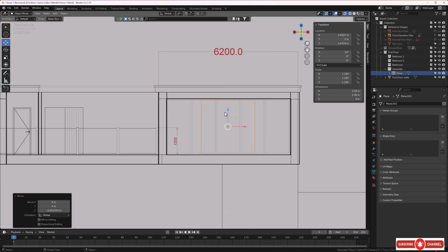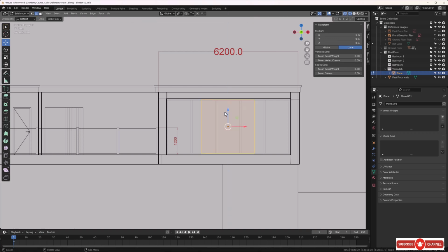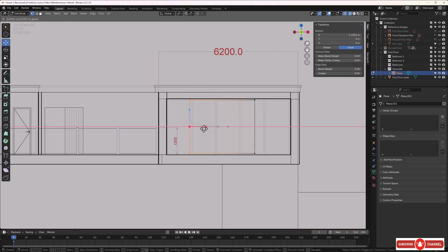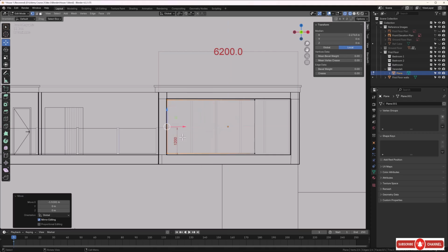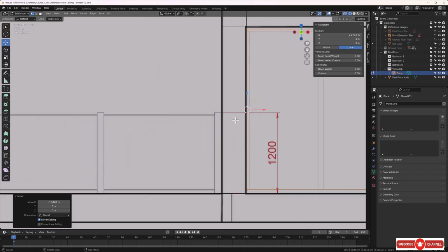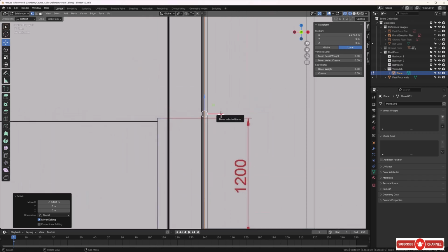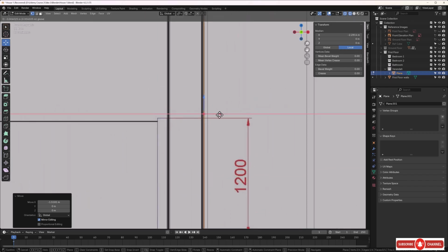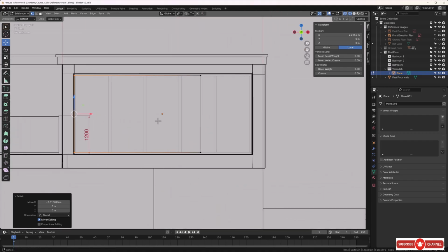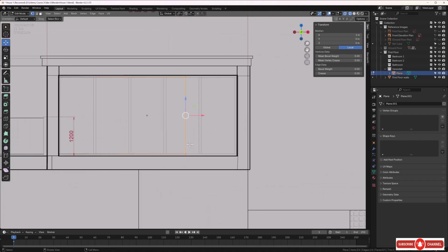And I think now let's just tap into edit mode. Press 1 so we can select vertices. I'll grab these ones here. Bring these over until this fits nicely into this hole that we've got for the windows. That's something like that. Let's grab this one too.